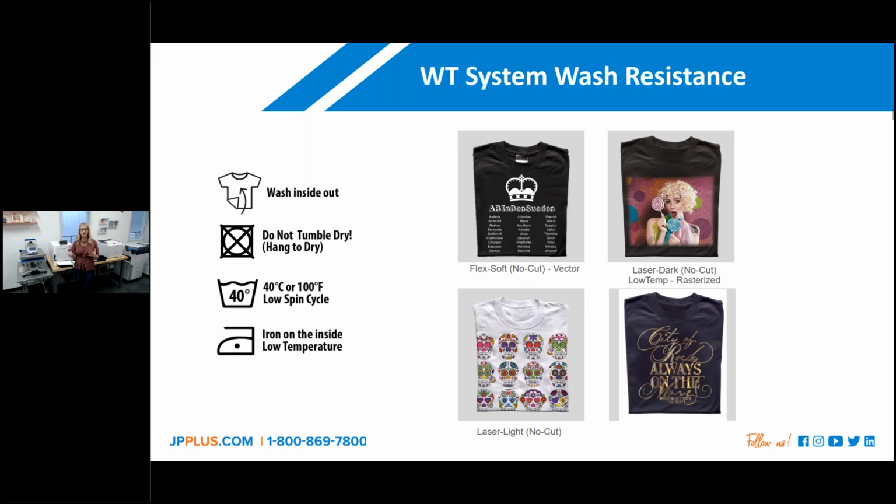So with heat transfer, something I really like to go over is when you're using it with garments, which is about 90% of what folks use heat transfer for, it's going to be on the surface of that substrate. So you're going to have a wash life with that. If you're using the two-step garment paper, just the standard paper, it's going to last you about 40 to 50 washes prior to maybe some cracking or some peeling.